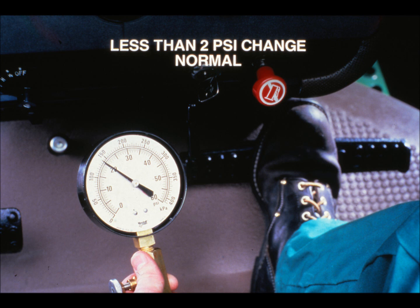If lube pressure changes by less than 2 psi, the system is normal and you can proceed to the next test. If lube pressure changes by more than 2 psi, that indicates a leak to sump from the control valve that caused the change.